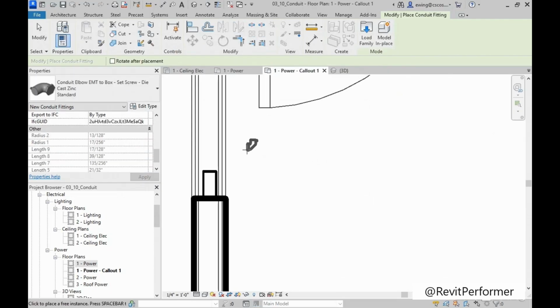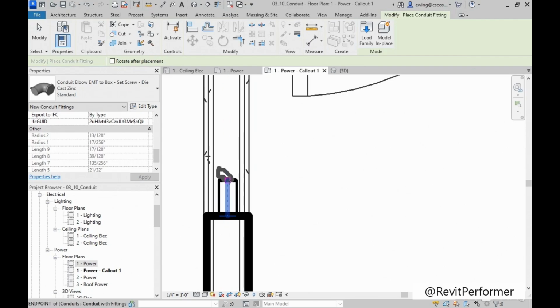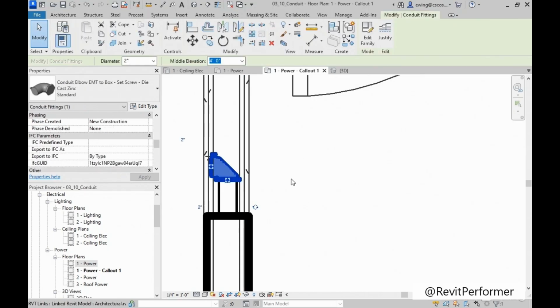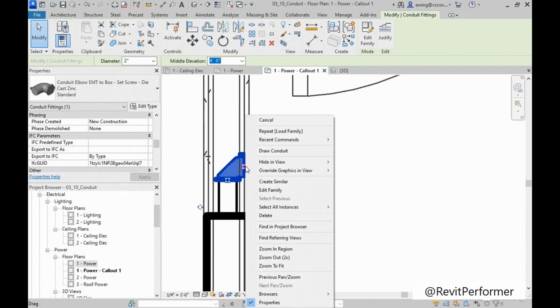Okay. Now let's move into this area here, and let's click it right on the end of this piece of conduit. Ooh, it's nice. It's going the wrong way though, so go ahead and select it. You can hit this little recycle button to rotate. It's going straight up or down. I'll chase it around over to here, click it again. Perfect. Now that's selected, go ahead and right click on that grip.